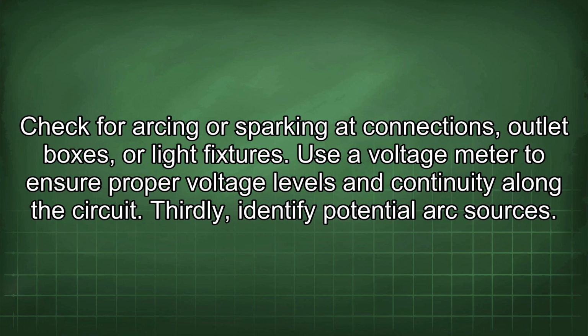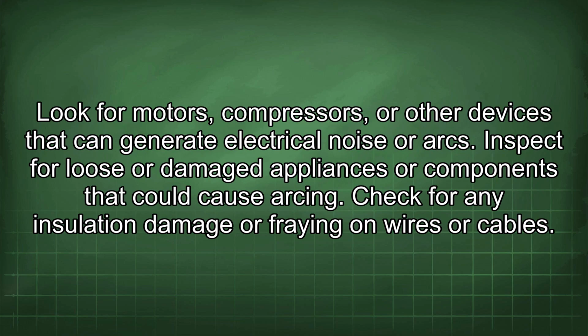Thirdly, identify potential arc sources. Look for motors, compressors, or other devices that can generate electrical noise or arcs. Inspect for loose or damaged appliances or components that could cause arcing. Check for any insulation damage or fraying on wires or cables.